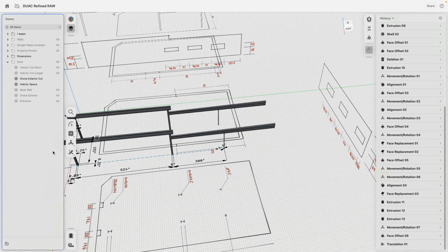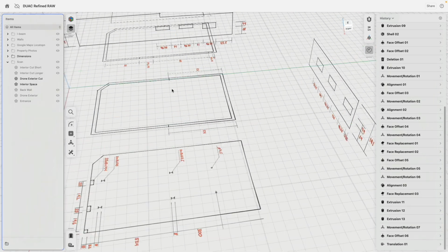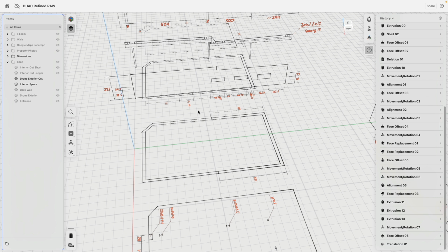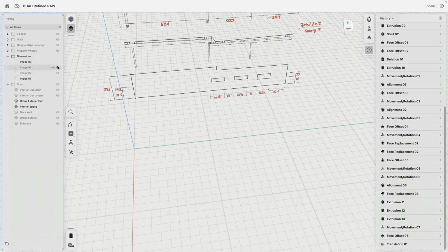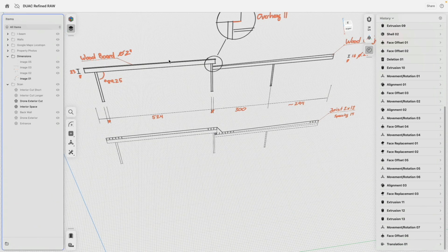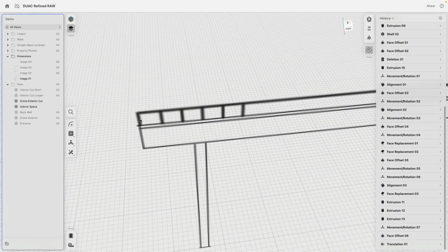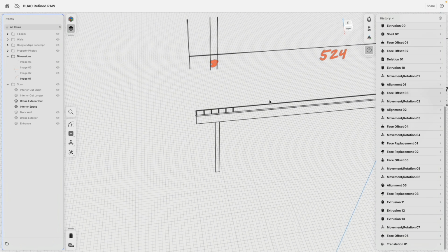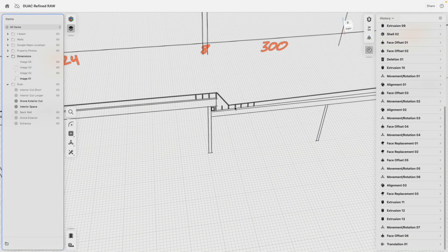Very good. So how do we do now the roof and the joist? It's actually going to be pretty easy and fast. That's the easiest one. I will hide, no, this one we need to see. Everything else I'm going to hide, and that's the last thing. So these joists, as you can see, they are perpendicular on these wooden spacers, and then we put later the wooden roofs over it. And these joists, we are remodeling them in a simplified way as one really long piece. And technically speaking, at the wall, they are also anchored at 1 degree rotation.